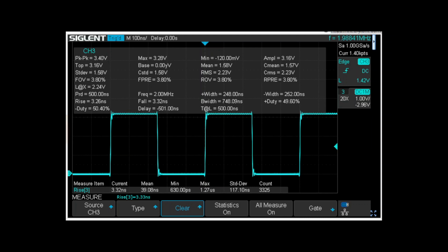Just one more thing I'll say before I end. When you're using a probe like this with that 1K resistor, the scope channel has to be set to about 20x. That's because the 1K resistor forms a voltage divider with the 50 ohm terminator, so the voltage that you sample is 1/20th. And so anyway, you have to set your scope the right way to use a probe like this, or your amplitudes will be wrong. I think the exact value to get a 20x probe is a 950 ohm resistor, but I didn't have one of those. So we'll end here.